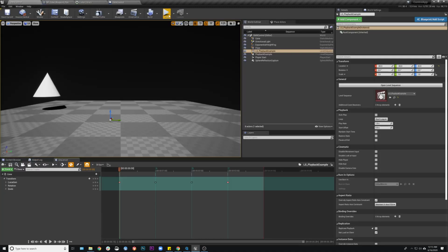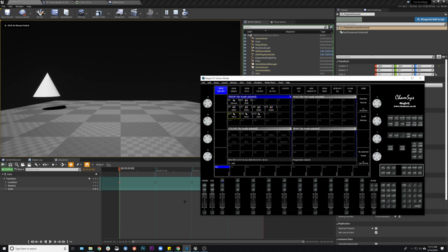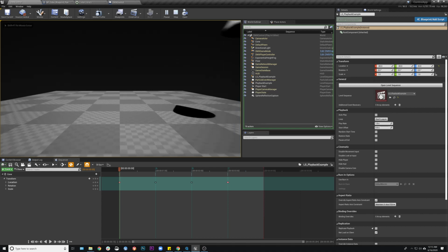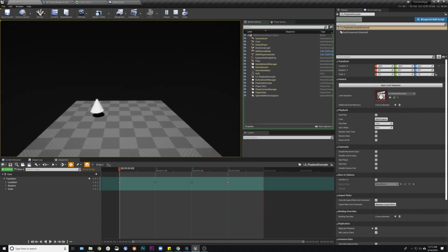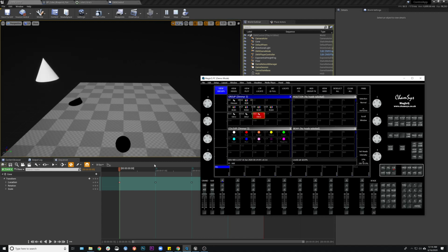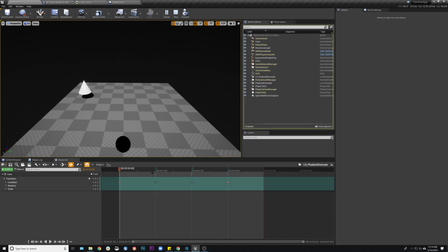So let's just go ahead and I'll run it. The cone shouldn't move. If I go to my canvases here, I'm going to grab that third channel I was talking about. And if I go at 10, it should start playing, right? If I move back, you can see a little bit more of what's going on. Again, it's not actually looping, but every time it gets back around, it's running a play command again. So if I wanted to pause it, I'll try and get it to pause in the middle. I can just say at 20, it pauses right where it is. If I were to clear everything, it's going to set it back to the front. And so this is one way that you can deal with playback here.